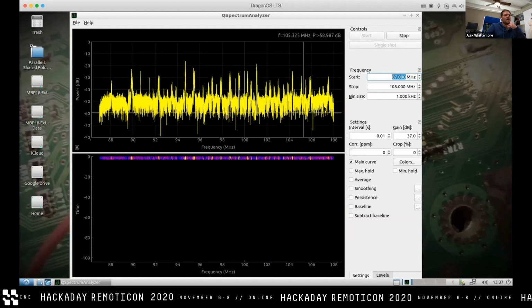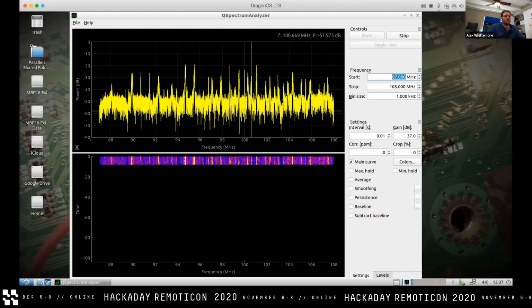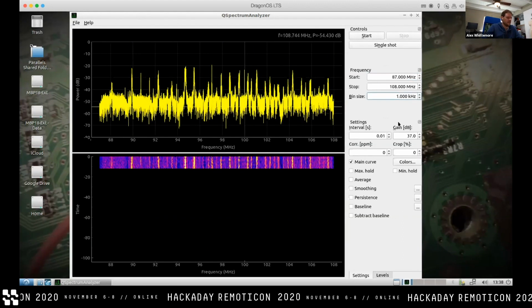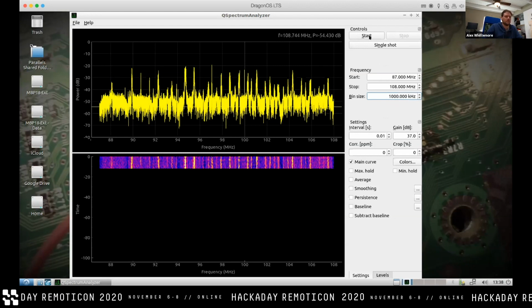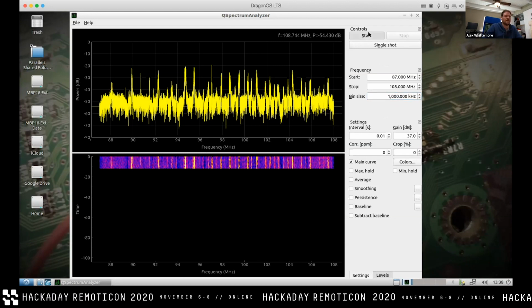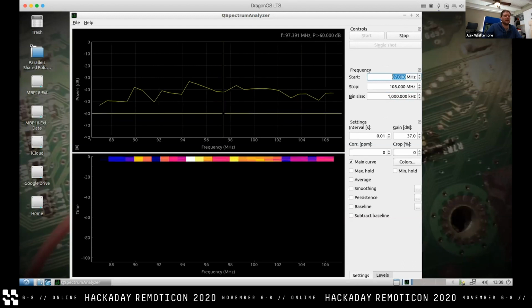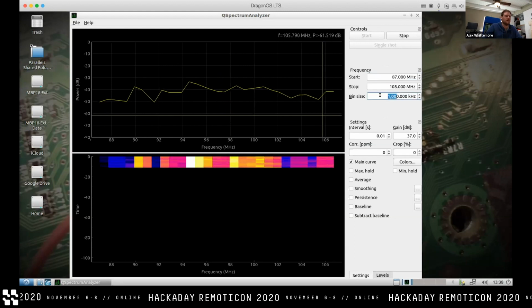Notice it updates much slower. So the frame rate has dropped precipitously. And if I stop it and knock that bin size back up to, hell, let's make it 1 megahertz. So this is going to be super fast to calculate math, right? Notice it still chunks in at like a frame a second or 2 frames a second or something like that. Clearly the math isn't the problem.